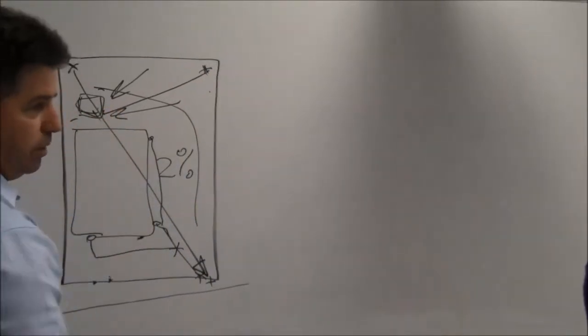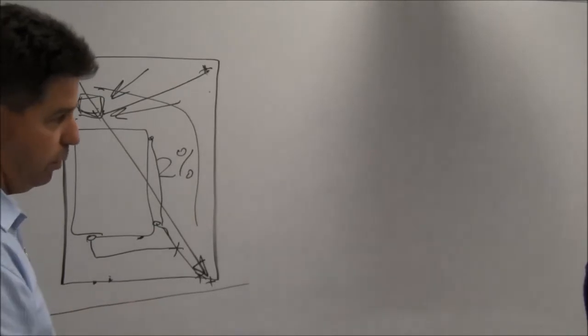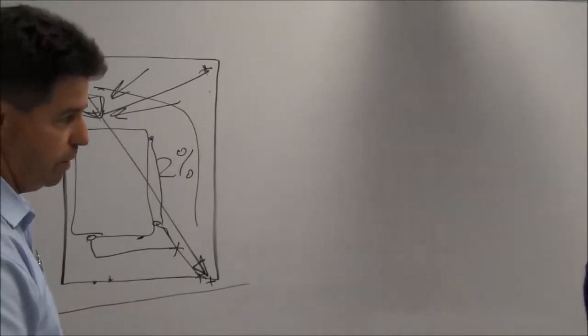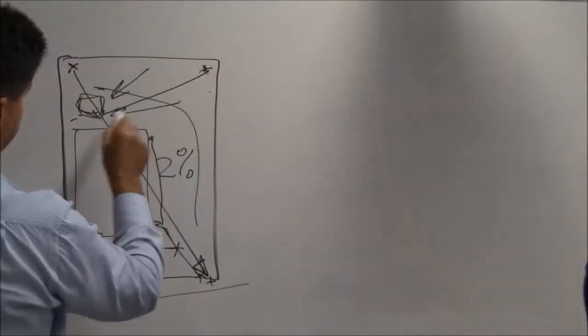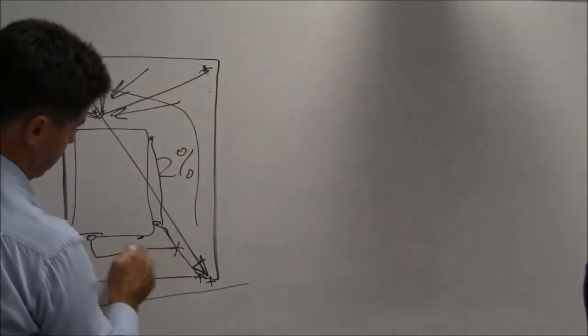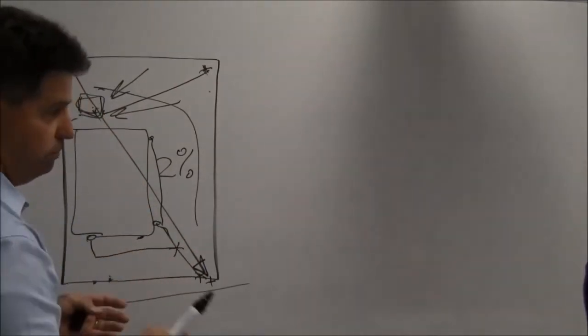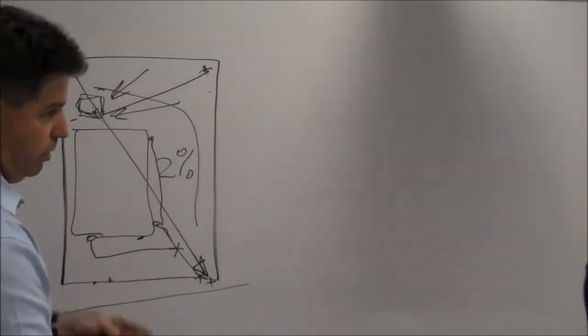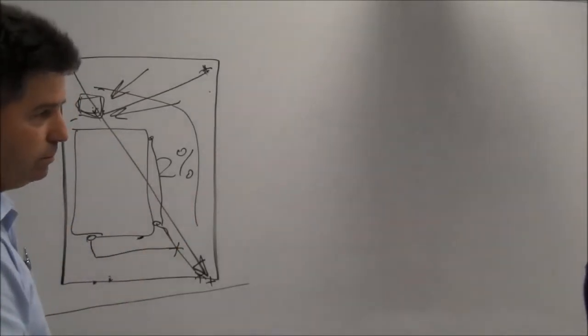Once it's in the pipe system, the time is obviously going to be quicker because it's travelling through smooth bore pipe and that sort of stuff. So by the time it gets from here to here into the pit, and then from here to here, it'll take a certain time, and if it continues to rain for 15 minutes, by that time the water's reaching the point all at the same time.